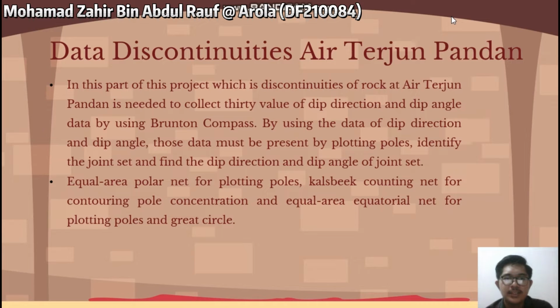This is the data discontinuities at Air Terjun Pandan. In this part of the project, which is discontinuities of rock at Air Terjun Pandan, we need to collect 30 values of dip direction and dip angle by using a Brunton compass. When we got the values, we need to present them by plotting poles, identifying the joint sets, and finding the dip direction and dip angle for each joint set.